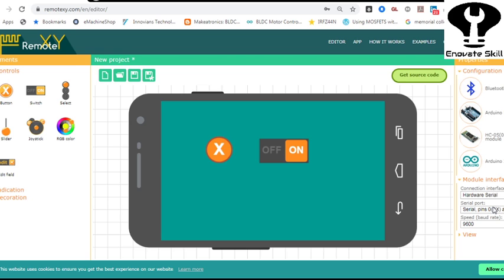I am repeating it, it's very important. At one time your serial communication device can communicate with only one device. If your Arduino is connected with Bluetooth, then Bluetooth communicates with Arduino and Arduino communicates with Bluetooth. But at the same time, if you want to monitor the serial monitor in the Arduino and send anything to the computer on the serial monitor, then it will not work. But if we are using software serial, then we can use hardware serial for computer communication, and we can use software serial for Bluetooth communication. That can be done. So that is a very interesting part.